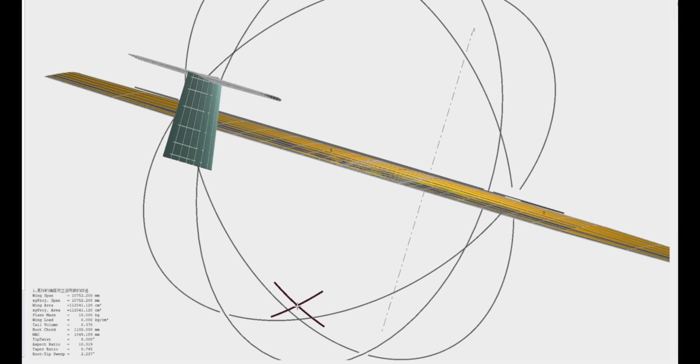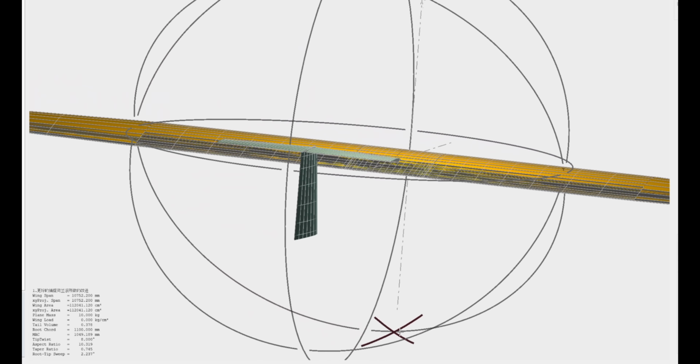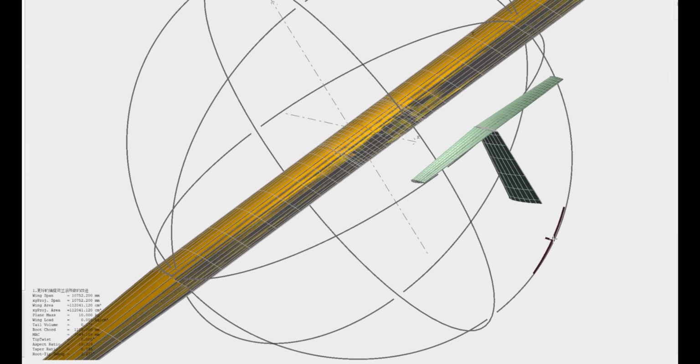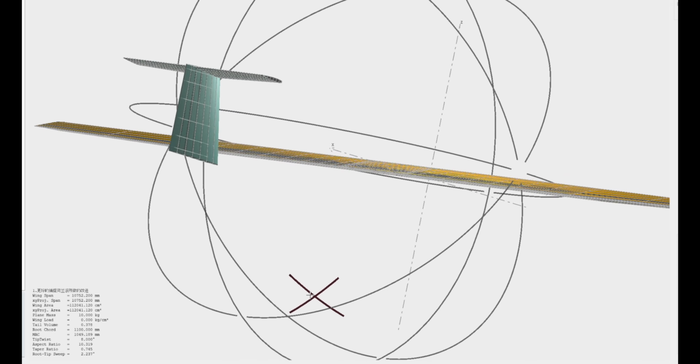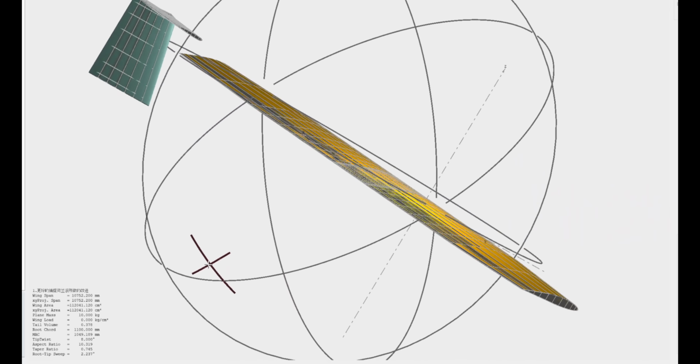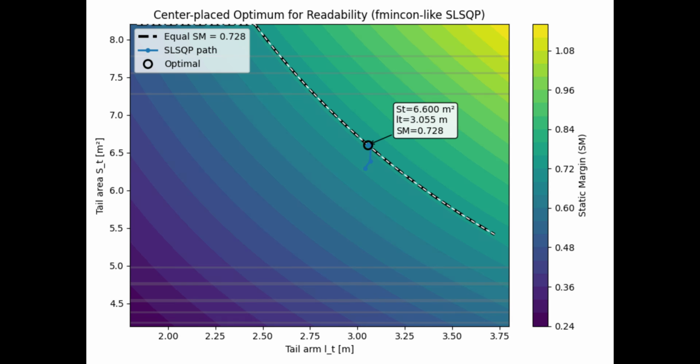Here, the tail arm and the tail area are not fixed values. They are two interdependent parameters. Using empirical formulas is, of course, the most convenient approach. But the most suitable calculation would be to solve it using an optimization algorithm that considers all results in order to find the set of optimal solutions under multiple constraints. I won't go into further detail here.